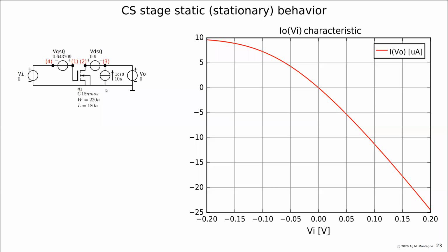So here we already see the source capability, and that's what we also studied before, is limited by the bias source, and the sink capability is limited by the transistor. And of course by the load, but in this case we have a load of 0 ohm. And here you see that this curve is like a parabola. So this is like, it is working in the strong inversion region. We have a quadratic characteristic. We change the voltage, then the current increases, but with an offset and a negative and an inversion. So as a quadratic function.